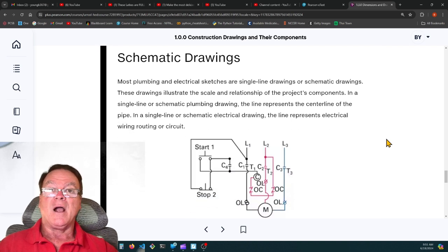It's difficult. Sometimes when they make a copy or print it out, they have a large printer that will print 18-inch by 24-inch. It can do drawing sizes or blueprint sizes. I've seen it where the computer put a margin around the drawing. So they had the drawing scaled exactly in the computer, and when it printed on the printer, the entire drawing was half an inch narrower. So nothing scaled exactly right.